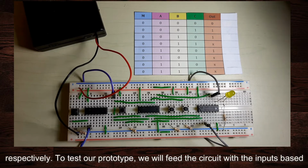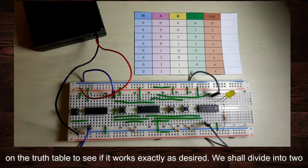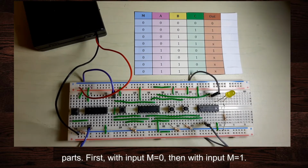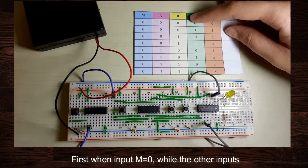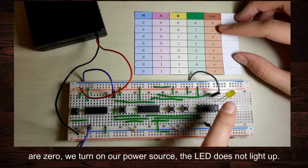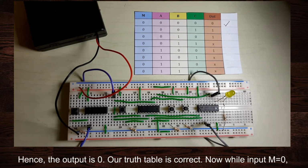To test our prototype, we will feed the circuit with the inputs based on the truth table to see if it works exactly as desired. We shall divide it into two parts: first, with input M equals 0, then with input M equals 1. First, when input M is equal to 0 while the other inputs are 0, we turn on our power source. The LED does not light up. Hence, the output is 0. Our truth table is correct.